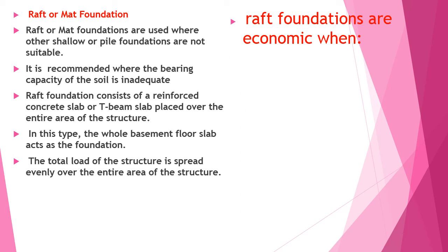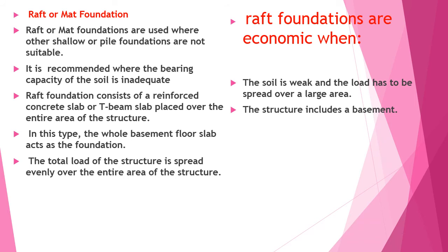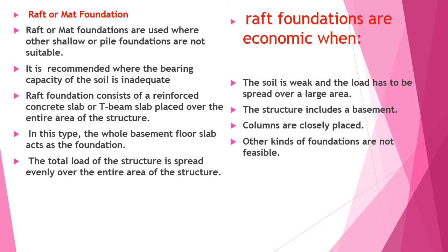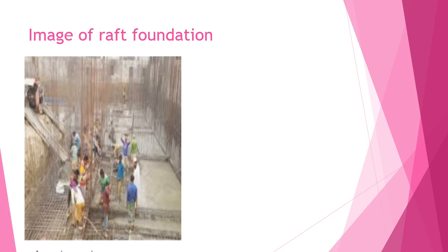Raft foundation is economical when the soils are weak and the load has to be spread over a large area, the structure includes a basement, columns are closely placed, other kinds of foundation are not feasible, or differential settlement is to be prevented. Image of the raft foundation has been shown below.